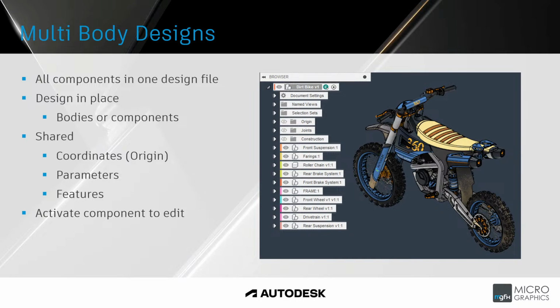Doing multi-body design, every component you activate will have its own timeline, its own history at the bottom of the screen, and any features you add while that component is active will be added to that timeline. The same goes for sub-assemblies. You can activate sub-assemblies or components within sub-assemblies, and those features would be added within the active component or sub-assembly as you add more features to the timeline.